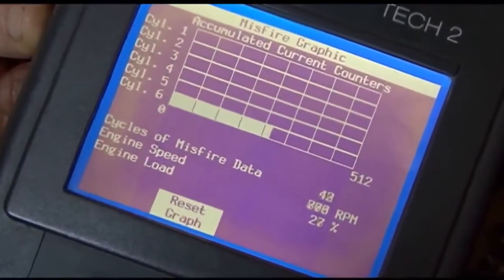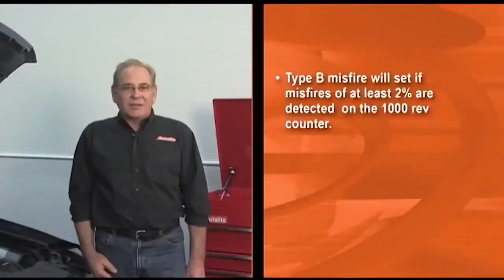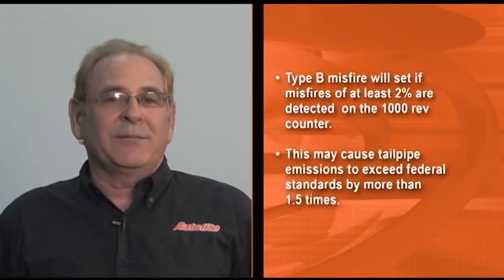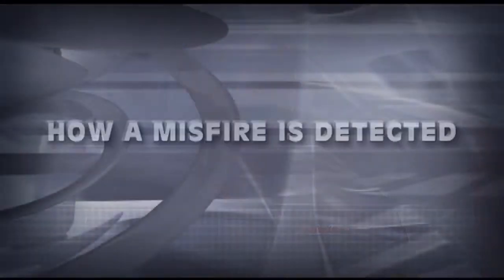Type A misfires will readily count up on the 200 rev counter in scan data. A Type B misfire will set if misfires of at least 2% are detected on the 1000 rev counter. This may cause tailpipe emissions to exceed federal standards by more than 1.5 times. The check engine light will be lit and the car may or may not run poorly.